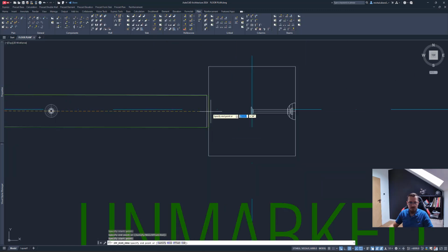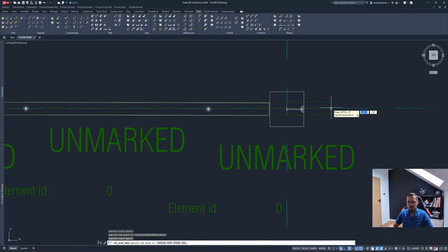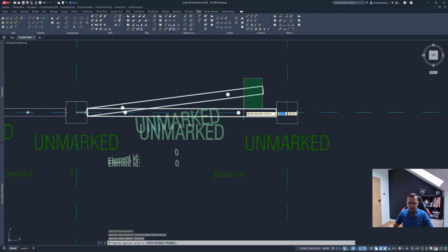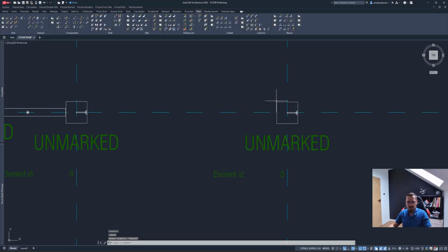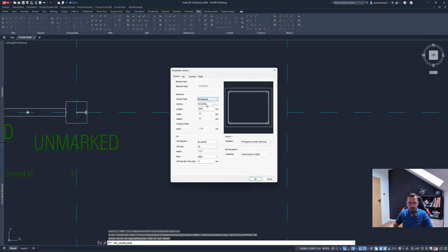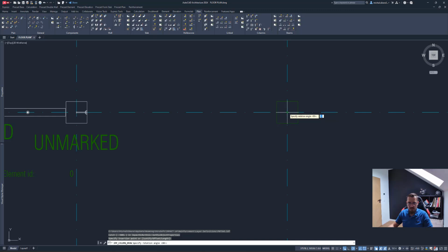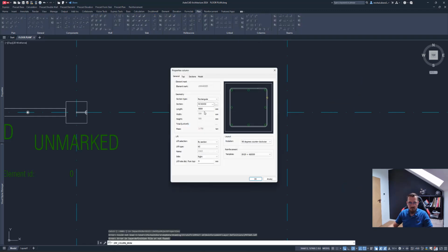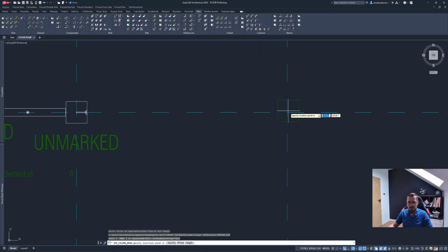Of course, if I want to snap those elements now, oh, my column is off. I'll need to correct that as well. Okay, yeah, that's a mistake. Let's delete this, and let me delete this column as well. Now let's place that column. Now let's go with the 50-50. Let's go 6,000. Yep. Apologies for that, I want everything to be aligned nicely. Yep, that's my column.